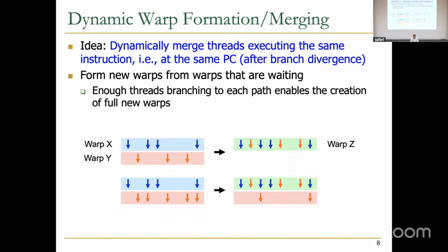But you may say, okay, it's a bad idea. We didn't gain anything. On average, our utilization is bad. On average, the utilization of the thing on the left over here is the same as the utilization of the thing on the right over here, right? On average, that's true. But if you had one more warp over here, you could merge that nicely also. Makes sense now, right?